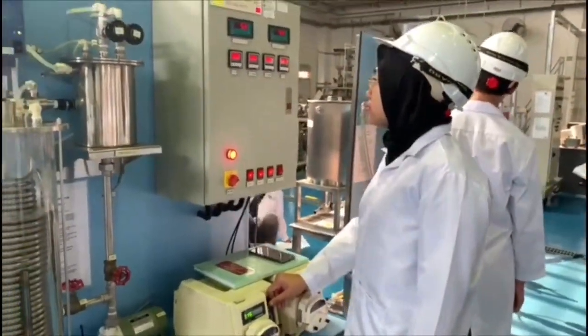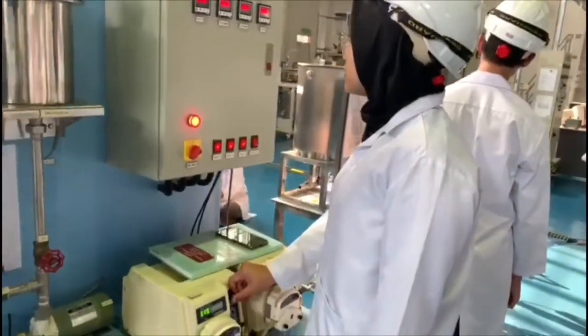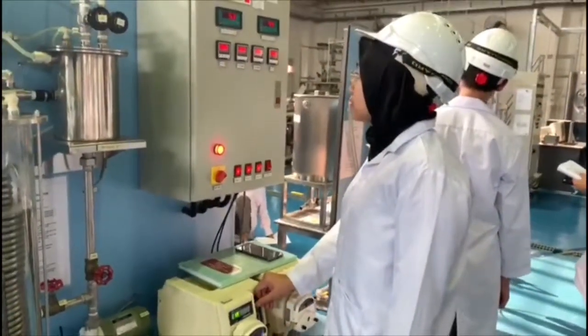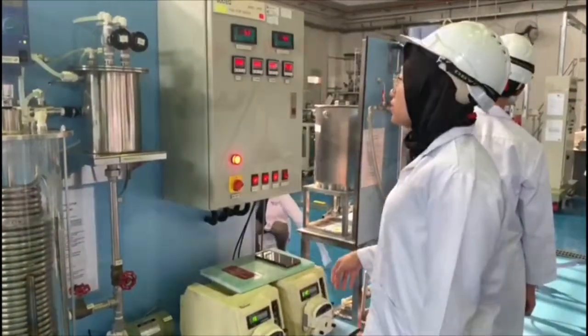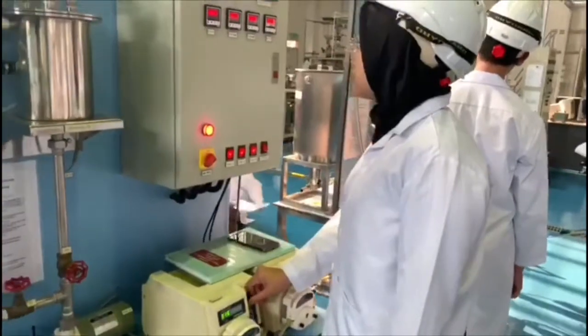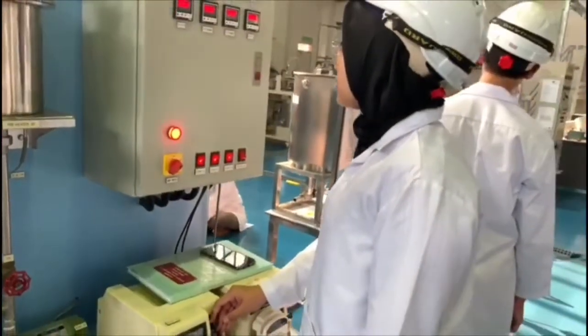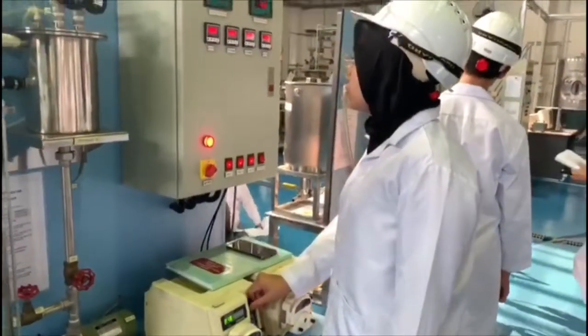Record the flow rates. Fifth, start monitoring the inlet Q1-01 and outlet Q1-02 conductivity values until they do not change over time. This is to ensure that the reactor has reached steady state. Sixth, record both inlet and outlet steady state conductivity values.